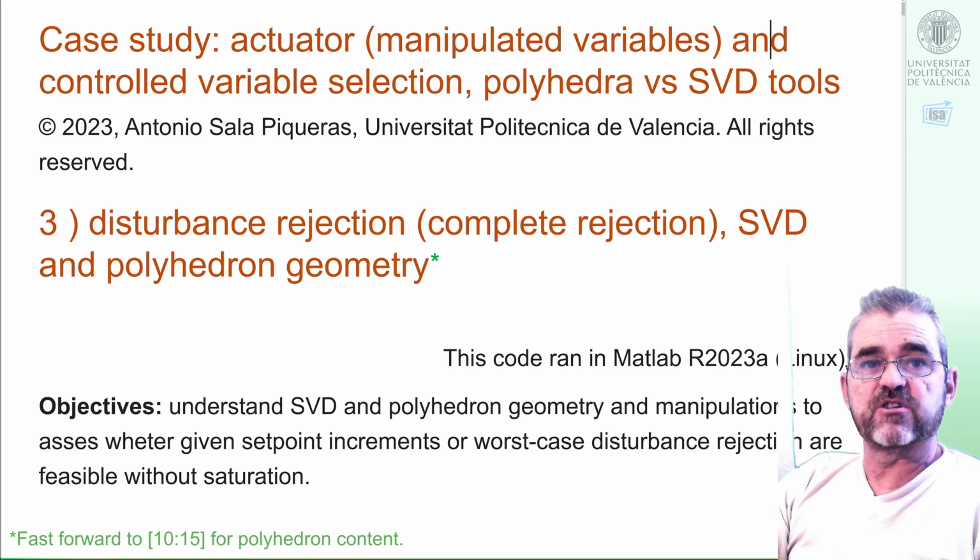Of course, the value of the input needed to cancel the disturbance is the same whether we are able or not to measure it. So we are not discussing how we'll be able to cancel the disturbance. Maybe we will do it with some integral action controllers or whatever. But the thing is that the equilibrium value to cancel them is given by U equal this feedforward matrix times the actual value of the disturbances.